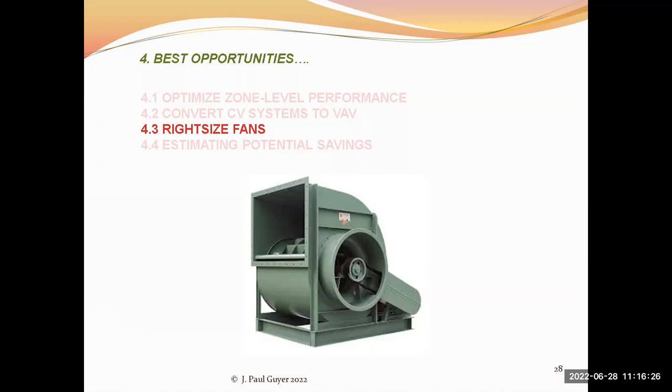All of this results in a reduction of the required cooling load on the building. And therefore, that means your older fan is too big and is therefore consuming too much energy.